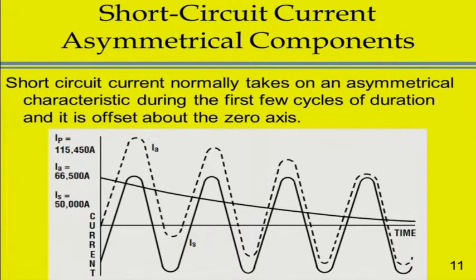And it's not just the motors and the transformers that have fields collapsing. Every wire that's in the building has a little bit of additional response that it gives to that fault, because the magnetic fields are collapsing around all of those things. So it makes all of the calculations a little bit complicated